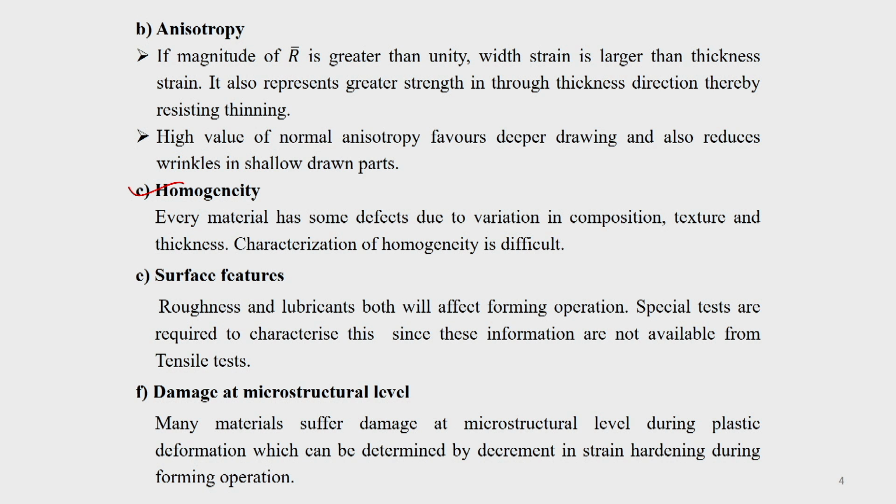Now, the damage at microstructural level also affects the deformation behavior or forming behavior of this thin sheet, because you will find that during the processing itself some materials might have resulted in some sort of damage inside itself, maybe at microstructural or submicron level during the plastic deformation, and these can be determined from the tensile test. So, how much is the damage which has come, okay? Because if there is any damage taking place, then it will be reflected in your stress strain curve, it will be reflected in your work hardening behavior.